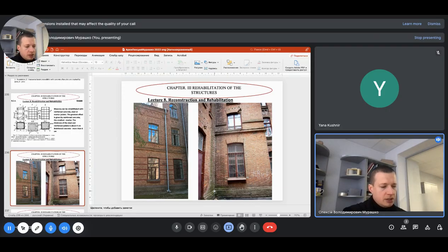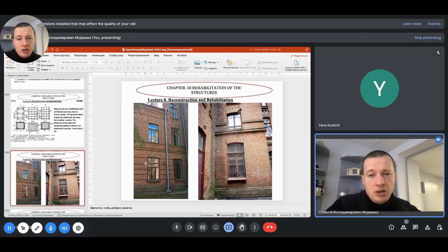It's a historical architectural monument, and that is why we can strengthen it by adding jacketing, because as an architectural monument its facades are protected, so we have to leave the external view of this building the same as before reconstruction. That is why we have added those elements made of steel, which increase the bearing capacity of those walls.